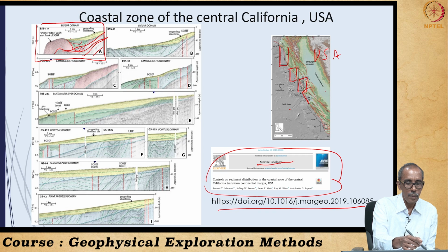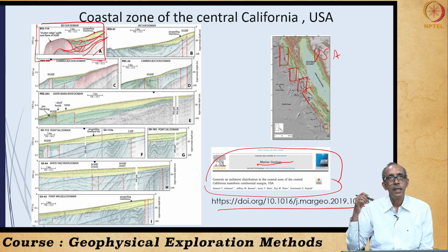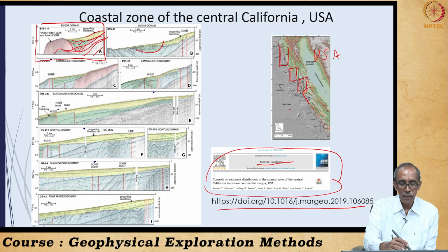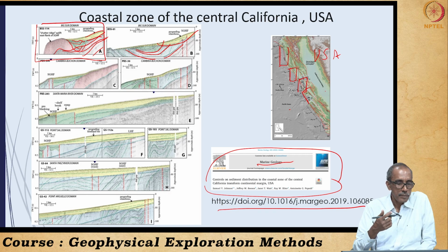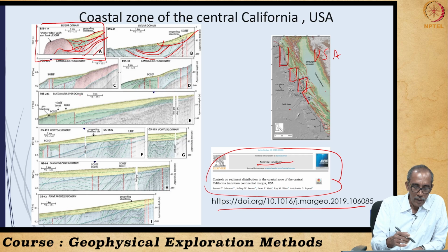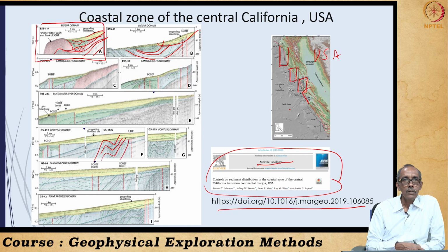This is maybe a valley cut basin, and these are the different layers. Similarly, in the next one, we could decipher different sequences, as I am marking. And obviously, we fine tune this interpretation, if necessary, with a couple of borehole drillings. Similarly, here we are able to bring out the folded structure in the rock from the seismic sections. These are the advantages of exploring the subsurface using the seismic reflection method.